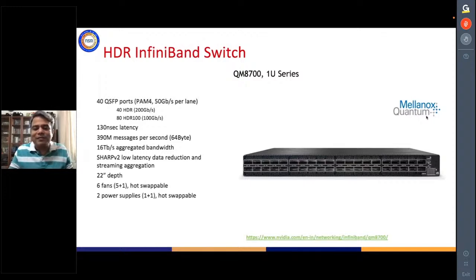Okay? The transceiver or the copper cable is receiving data from one server. The data comes in at a very high rate. We are looking at, let's say, 200 gigabits per second. The data comes in, and now the silicon needs to decide what to do with the data. So obviously it contains some sort of header. The header contains the source address and the destination address.